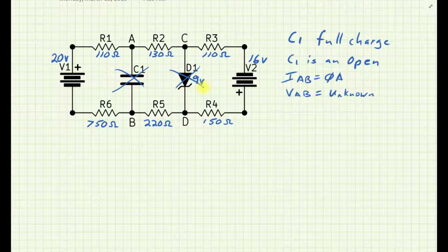Now there's three possible scenarios. The C to D voltage is such that it will forward bias, and then the diode will hold it to be 0.7 volts. The C to D voltage is reverse biased, and that diode will hold the 9 volts. And the third scenario is there just isn't enough voltage in either forward or reverse bias to cause that diode to allow any current flow, and so it will just remain an open.